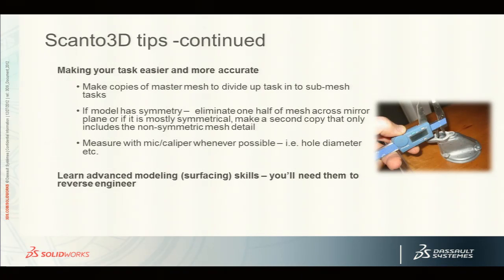Also, if you have very measurable parts of your model, like holes, and you've got calipers or a mic, use them. Don't rely on the mesh; rely on your calipers or your mic. The mesh isn't perfect, and you could probably get a better read off of a bored hole by just miking it, okay?